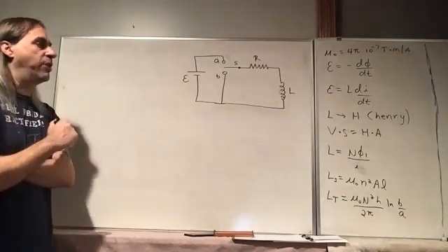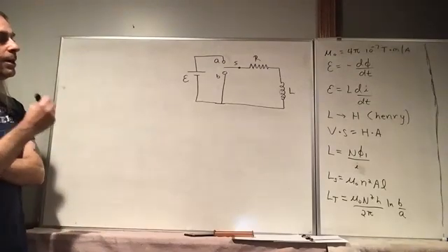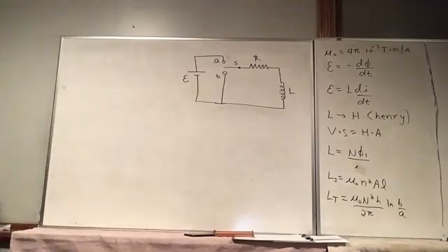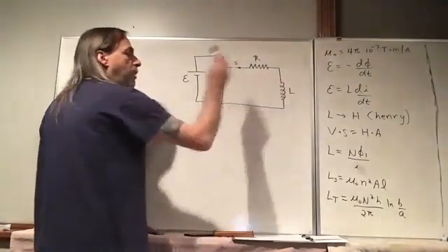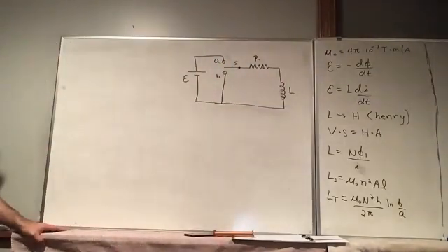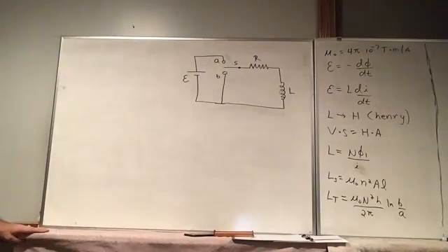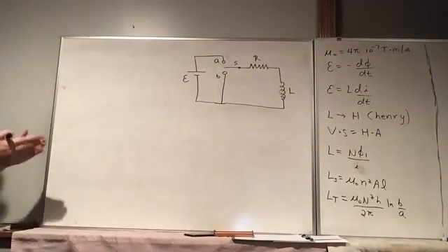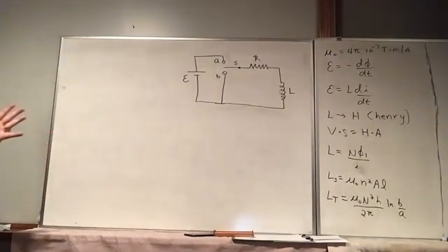We're going to get an equation, and we can get the exact same equation just using Faraday's law. But let's stick to the simple approach: we say there's a voltage drop across the inductor. Again, that's a little questionable to say, even though it works in practice, and we can get the exact same result without saying that. But mainly for what we're going to talk about in the next chapter, it's useful to have this idea of a voltage drop across an inductor.